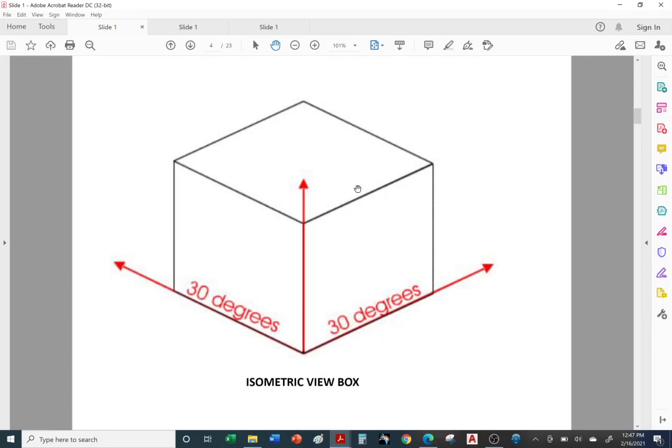You typically start with the box. It's a rectangular box. It doesn't necessarily have to be squared. Think of a rectangular prism. We're going to use 30-degree angles to draw our box. Imagine you're making this custom fit box for your part, like a glove to a hand.